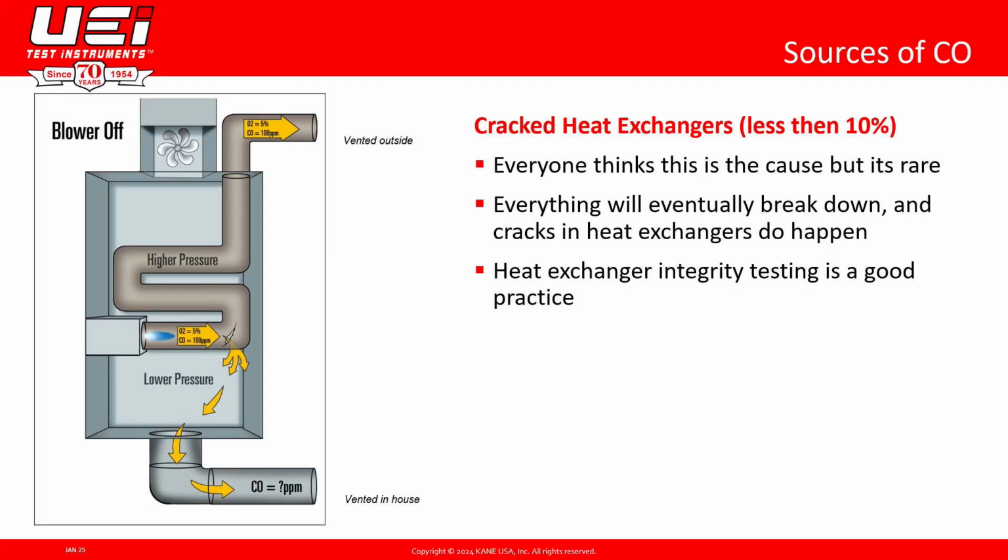And then the third most common reason that home CO alarms go off happen to be cracked heat exchangers. Now, cracked heat exchangers are a very real thing, but they only account for less than 10% of the reason home CO alarms go off. And cracked heat exchangers, by the way, we'll talk about this a little bit further into the presentation. There is a way to do a heat exchanger integrity test with your combustion analyzer.